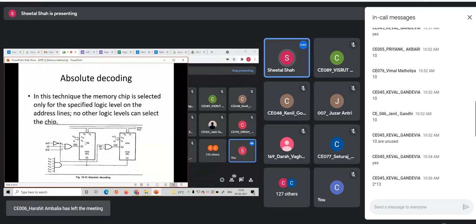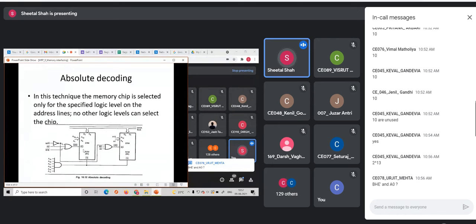As you know, we are supposed to connect two ICs, one for the even bank and the other for the odd bank. You can see that these 8K ICs are connected in parallel here. One represents the even bank, the other represents the odd bank. So can you tell me how we can make out whether the data is read from the even bank or from the odd bank? How to select an even bank or odd bank? A0 as well as the BHE bar signal.